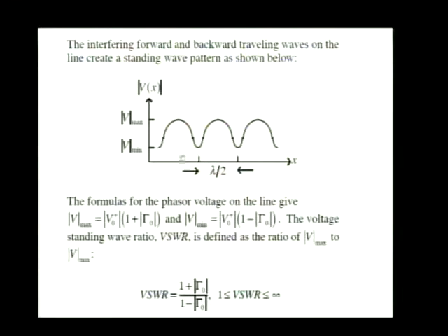What does that mean on the drawing up here? Remember, the standing wave ratio is Vmax over Vmin. That's another way of writing it. Vmax over Vmin infinite? What would Vmin be then? Well, once again, if Vmin was 0, then Vmax over Vmin would be infinite. That means in this standing wave pattern, those minima would go all the way down to 0. Okay?